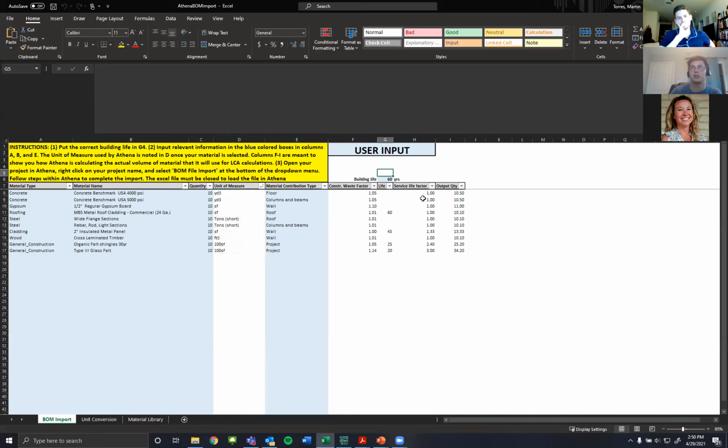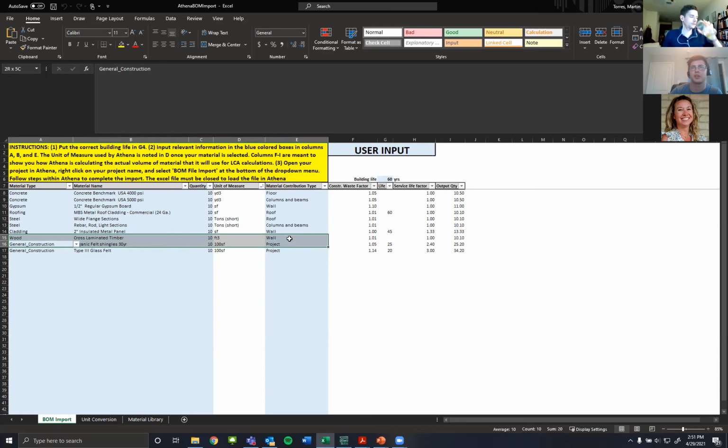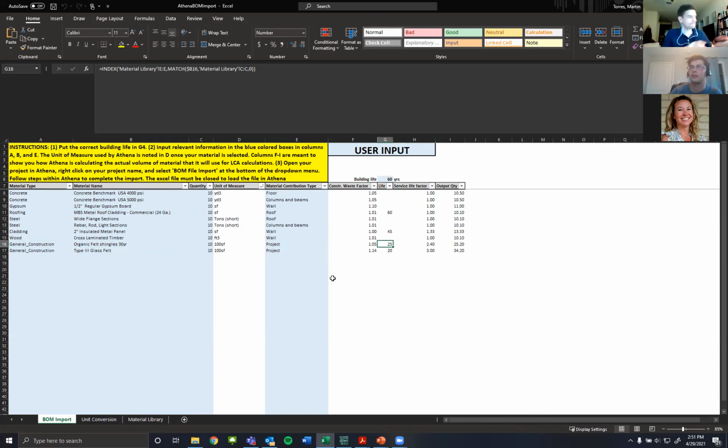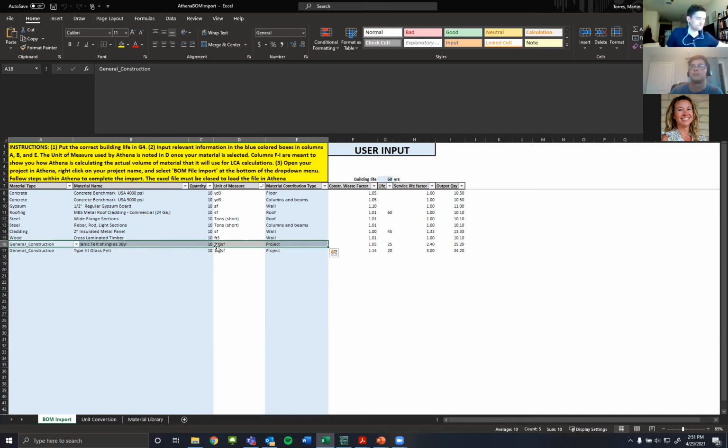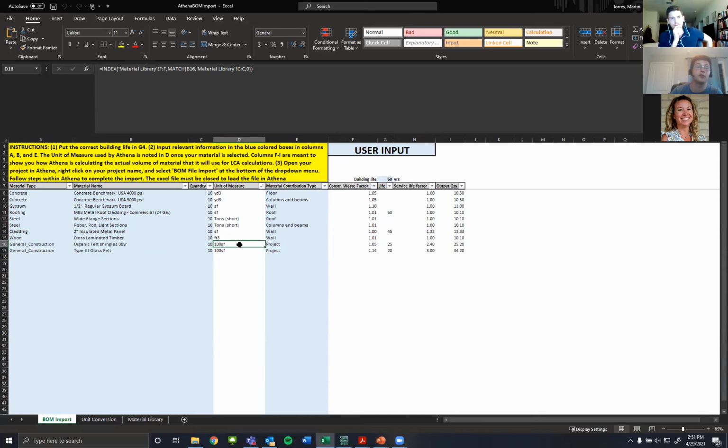And you can change, so the service life factor is how much is increasing. Like my building life is 60 years, this material life is 45 years, so it's going to multiply by 1.33, 60 over 45. But this is all going to update for you live. So we can see that organic felt shingles that have a 30-year lifespan, that funnily enough have a 25-year life, come in hundreds of square feet. That's the unit that Athena likes.